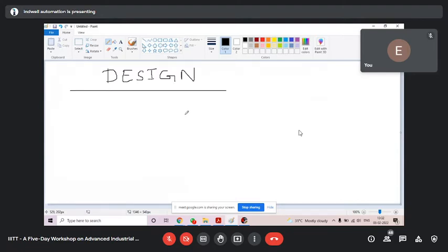Third thing you have to do, in these steps only we go in SCADA software. First we design the thing, we select the driver. Third is tag. Why I told tag lastly? Because in tag, driver will be required. When you create a tag, driver will be required. So better you do driver first and then you go for tag.